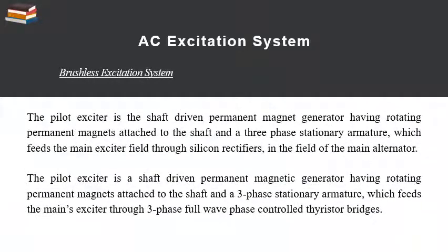The pilot exciter is the shaft driven permanent magnet generator having rotating permanent magnet attached to the shaft and a three-phase stationary armature which feeds the main exciter field through silicon rectifier in the field of the main alternator. The pilot exciter is a shaft-driven permanent magnet generator having rotating permanent magnet attached to the shaft and three-phase stationary armature which feeds the main exciter through three-phase full-wave phase-control thyristor bridge.